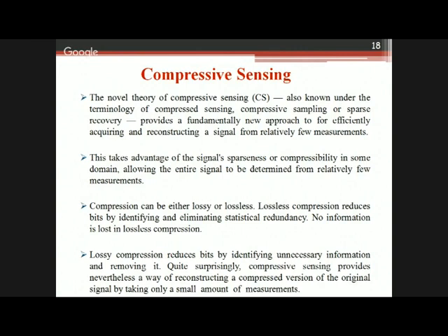If my bits are occurring again and again, then less importance is given to them. So we are basically removing that part of the information, as it is not important anymore. Compressive sensing is actually a type of lossy compression, where we just remove the unnecessary information, but we are still able to generate our original signals on the basis of those random matrices. You can see it in one of the functions of MATLAB, or by using L1 minimization reconstruction algorithms.